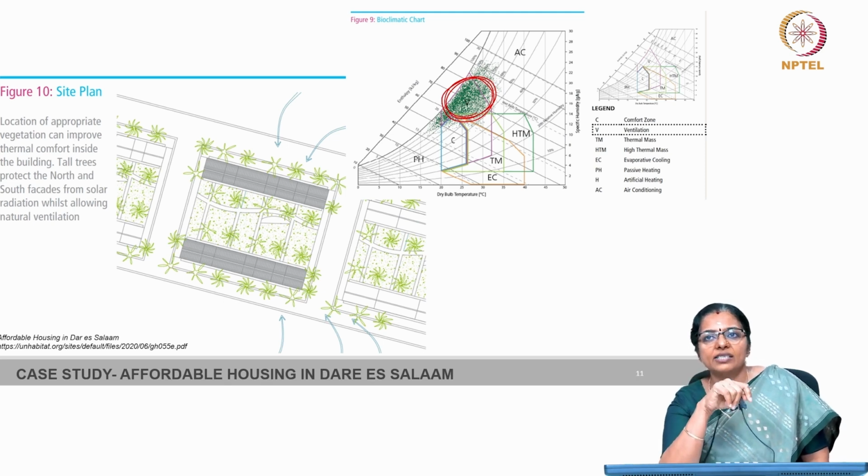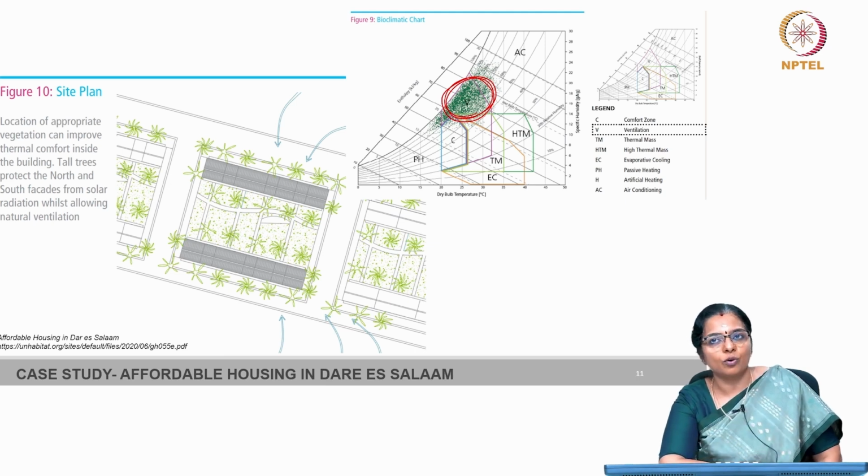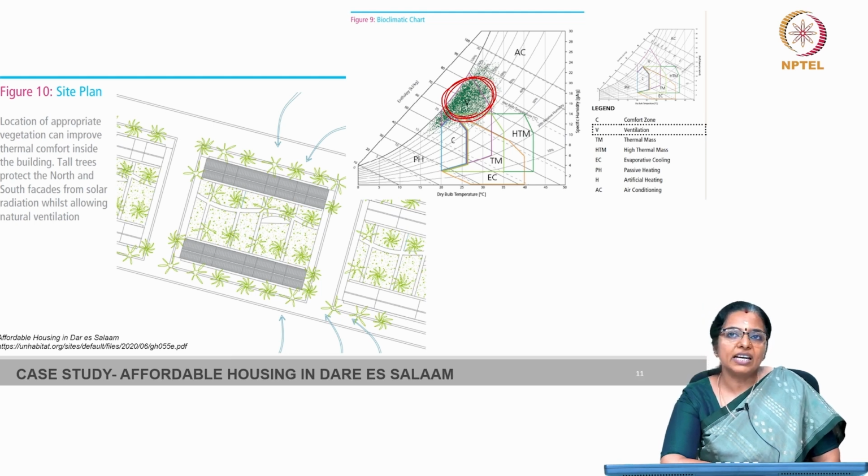So, the primary design goal for this zone is to facilitate the unrestricted flow of air within the house, while concurrently preventing internal surface temperature from exceeding outdoor temperature, because outdoor temperature is very high. This protective measure extends to all building facades, shielding them from excess solar radiation. Buildings within this zone should prioritize being lightweight, with minimal thermal storage capabilities.